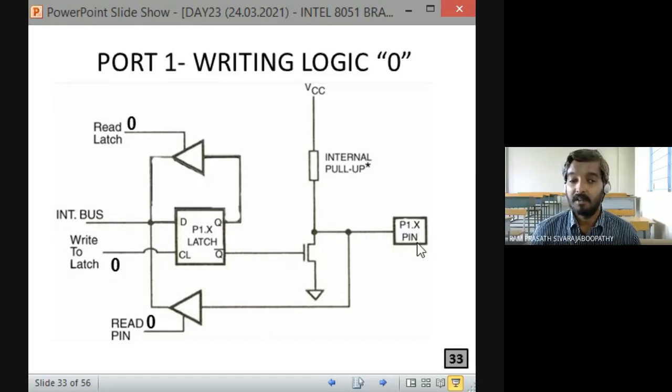Fine. I have told all of you two wordings. So where does the write operation always happen? You would have written it down; I told you that wording when you came to the lab. Write operation is always on the port register. What about the read operation?